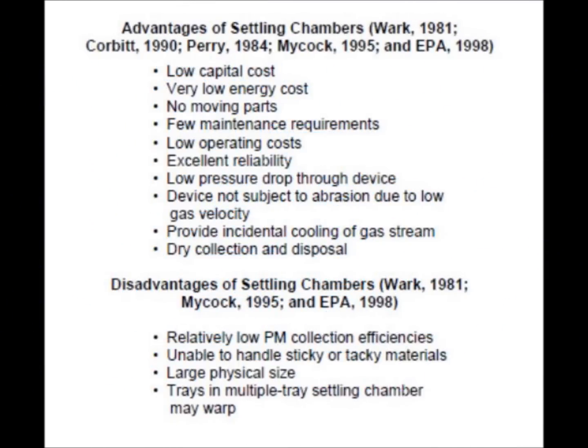Gravity settlers offer many advantages. It is economic since it has a low capital cost and a very low energy cost, as well as low operating costs. Moreover, it has no moving parts and has excellent reliability. However, gravity settlers have relatively low particulate matter collection efficiencies and are physically large in size. It can't handle sticky or tacky materials. Furthermore, there is also the danger that the trays in a multiple tray settling chamber may warp.